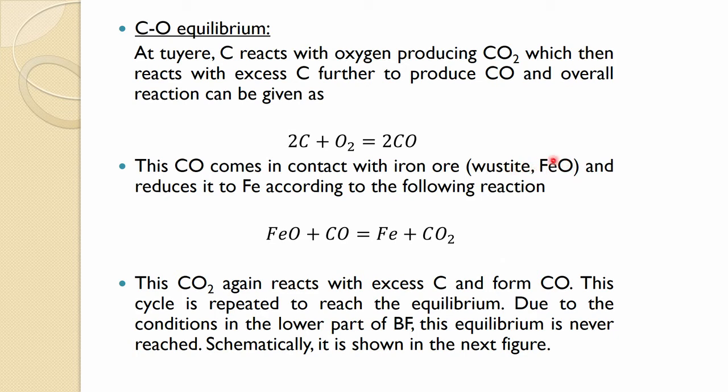It makes a low eutectic solid. So, it starts melting at the upper boundary of the cohesive zone, and at the lower boundary of the cohesive zone it becomes liquid. In that, most of the iron is in FeO form, not any other oxide, and of course the remaining bit is some liquid iron.